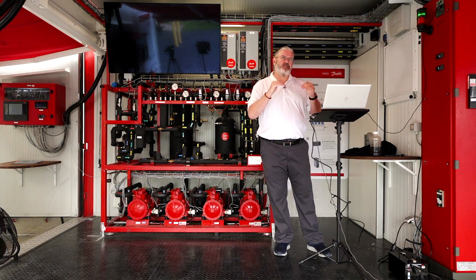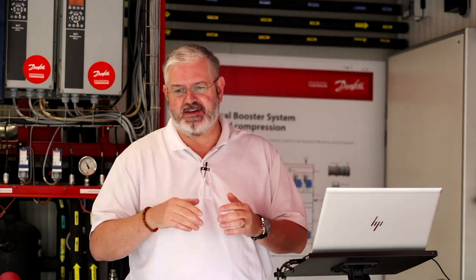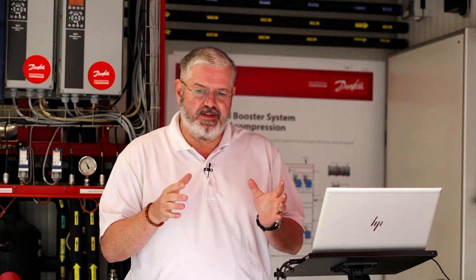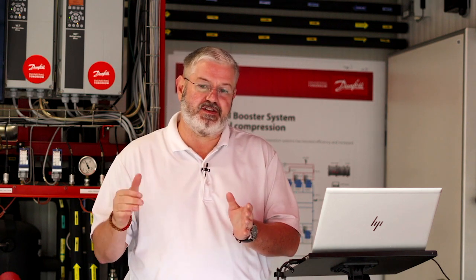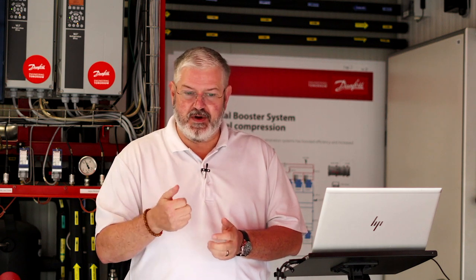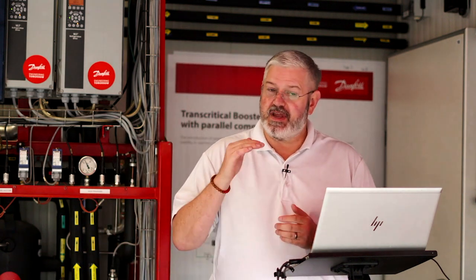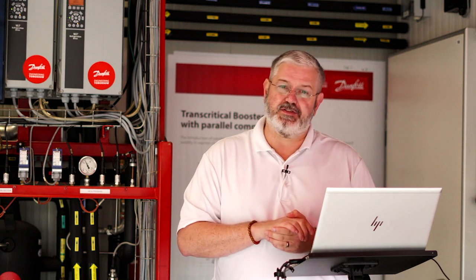I personally struggle to see where that would be used, other than maybe like a C-store application, you know, box by box. And I'm assuming on that a small condensing unit with CO2 is still going to have some type of high pressure valve to give us liquid, but also to maintain just a limited amount of pressure on the TXV. But the mechanical TXV for CO2 exists today and is available. It is brought to you by Danfoss.